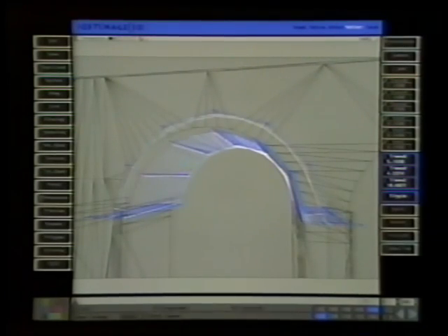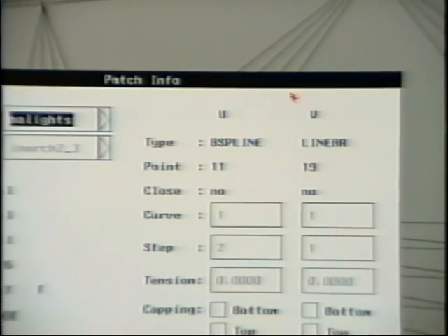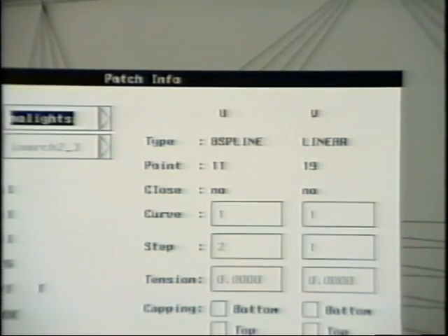Now let's make visible the stone arch on the underside of the bridge. It's a patch surface, B-spline in the direction in which it's curved, and linear for the direction it runs down and back. We'll give it a 2D global texture and select a stone wall texture map. First off, let's make the map darker and put some texture into the specular highlight.